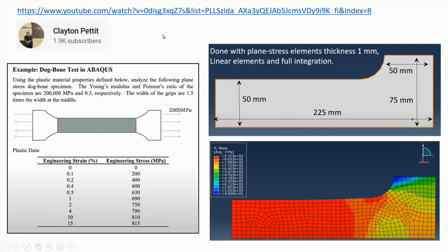Now, in 3D Experience, we do not have the plane stress or plane strain elements. Therefore, to replicate that, I can either use solid elements to solve that problem, or I can use shell elements, flat shell elements, which are being pulled from both sides. Essentially, it's a membrane element, and it replicates the plane stress condition very well.